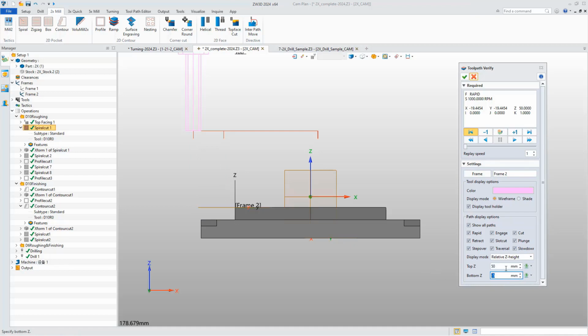If we set it as relative Z height, the Z0 is the clearance plane of current frame. And it will show the toolpath between the top Z and bottom Z. Like here, we set 0 and -55. The final one is to set the range by the location number.